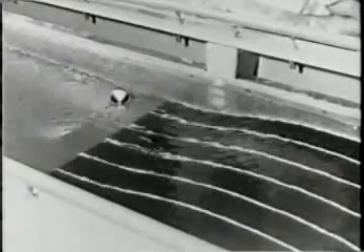Now I'm making a vortex with a sharp-edged plate. This vortex has its axis vertical. As it goes up the hump, the length of the vertical vortex line decreases, and so the vorticity decreases, as you can see by the spin.